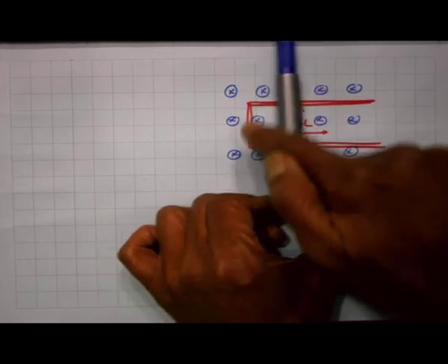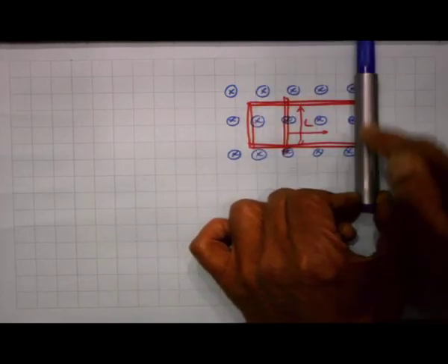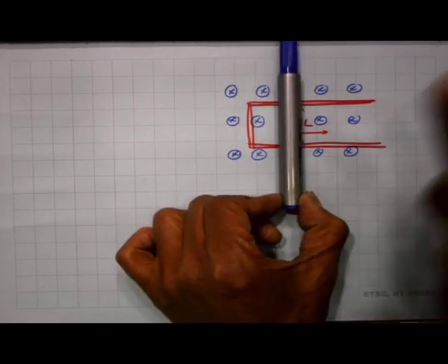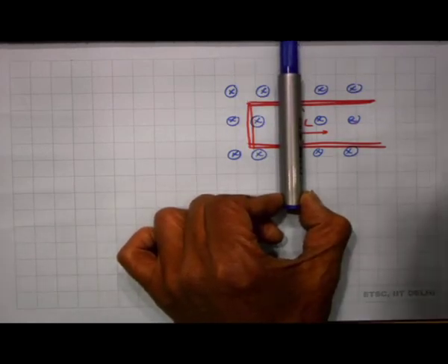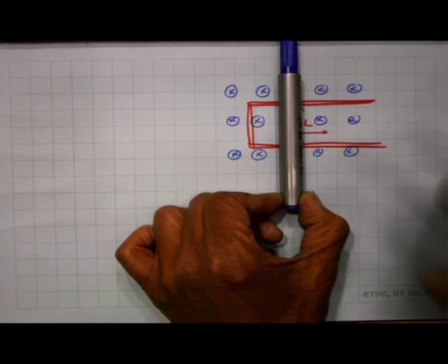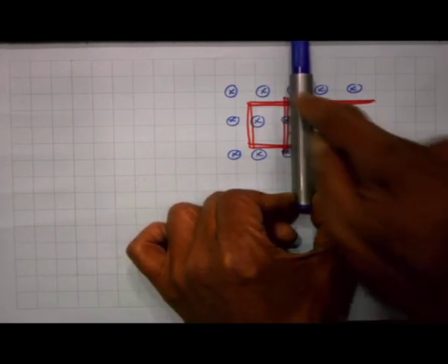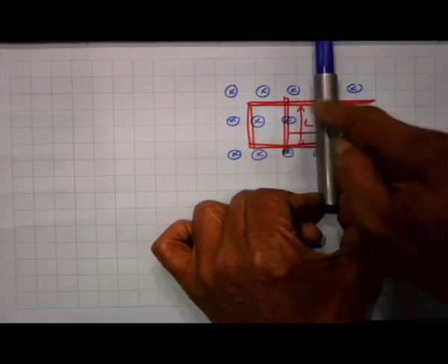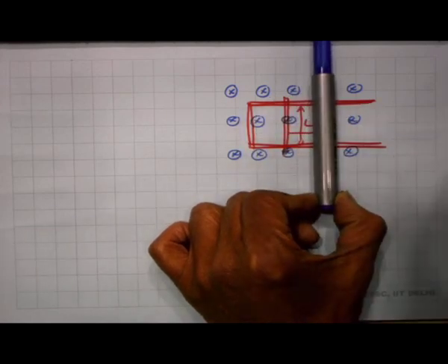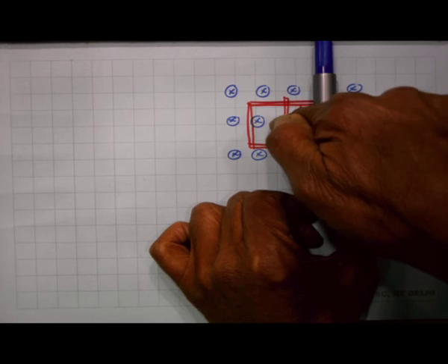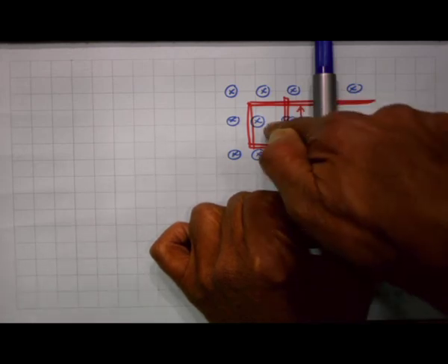So, as I move the conductor, there is a current flowing through the conducting loop because of Lorentz force. The equivalent interpretation is that as I move my conductor to the right, I am increasing the magnetic flux through this area. If I define my area as downward, magnetic flux is positive.